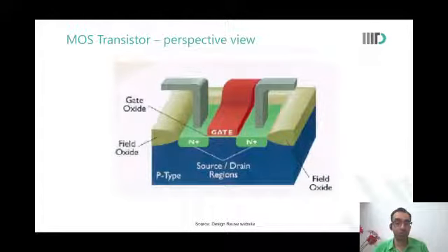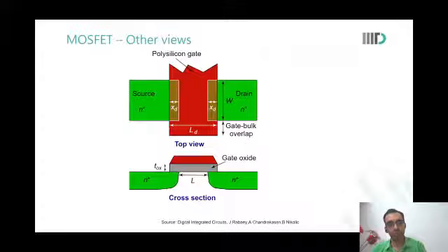Right, sir. Okay. So sir, this gate to drain capacitance in the model, that was consisting of this overlap and this coupling, the other coupling. The total CGD would have both components in it, the overlap capacitance and the polygate to metal and to contact and polygate to diffusion layer capacitance. Everything will be there in the total CGD.